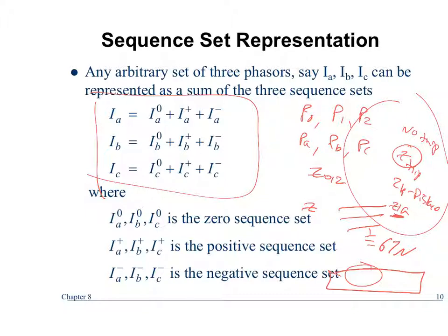So the relay specifies the circle or the box, but guess who actually specifies the circle or the box? The engineer. Yeah, the engineer picks the characteristic, and guess what else the engineer does? Picks the size of the box or the circle. And is it skewed? Is it offset? Does it look in the reverse direction? Do we have to do something called, I'm going to say this incorrectly, let me think of the term, load encroachment? All right? We don't want to trip on load, do we? But how does the relay know if it's a fault or a load?